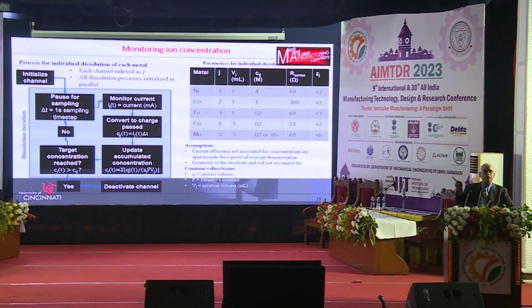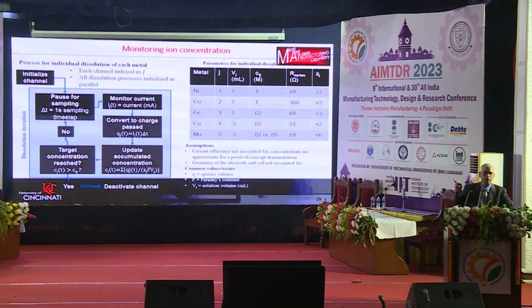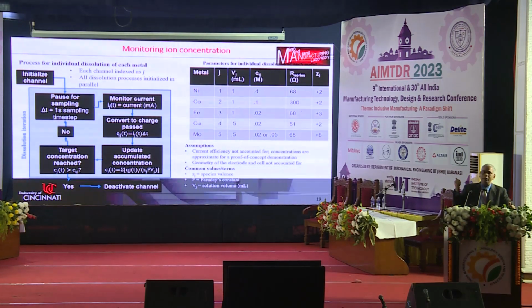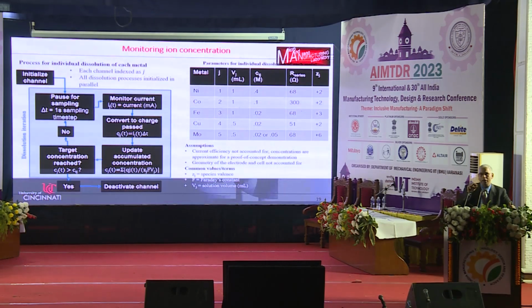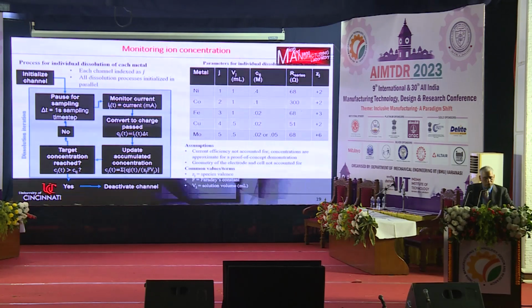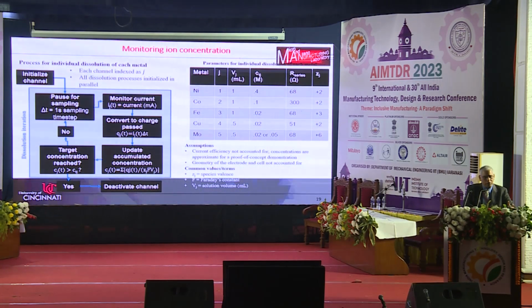This is the good thing with using the salt solution, right? If you have the salt solution, it is very, very easy for you to prepare the electrolyte with whatever molar concentration that you want. Your basic chemistry will tell you that. But if you are following this approach, then you have to have a mechanism that will tell you, okay, this is the amount of iron that will go into it. So this is the logic that we used here. Basically, it follows Faraday's law.